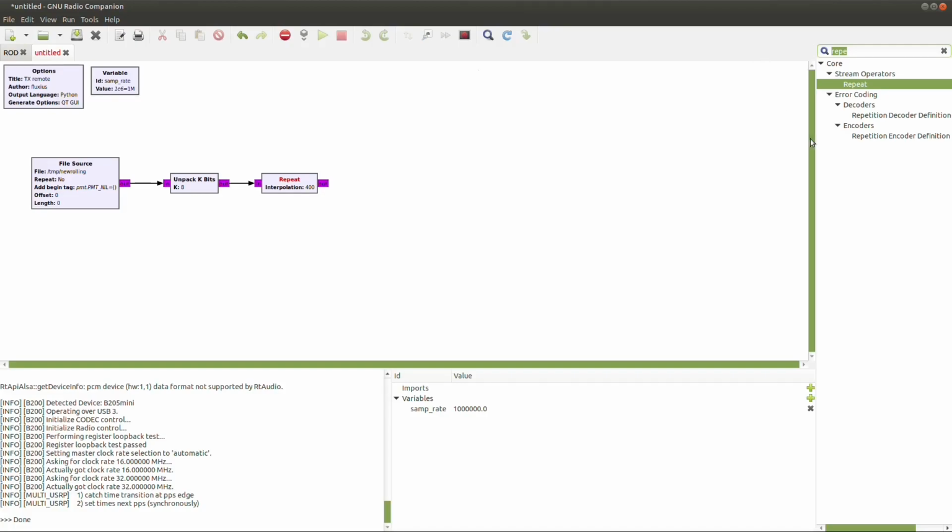We'll make use of UChar to Float in order to change it to float, because then we'll use a frequency modulator that uses only floats, and then we have to recenter the signal to 0 and also preserve the bandwidth from the maximum deviation.